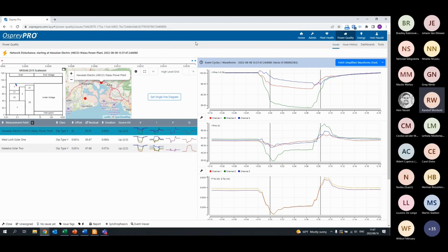A large inverter manufacturer brand standard setting in a case like that switches the inverter off for 10 minutes. Now, if you are in a part of the network that has a lot of these dips, that can really cause some downtime and loss of revenue for your client. Just something to consider: low voltage ride through and high voltage ride through settings.